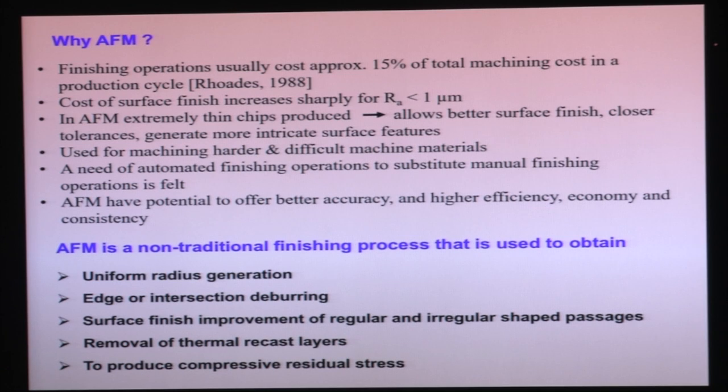and then we shall discuss the applications of this abrasive flow finishing process. So first, why does this abrasive flow finishing process come, why do these super finishing processes come? These super finishing processes are required nowadays because the surface finish requirement is in the range of nanometer. Sometimes we need angstrom level surface roughnesses. Suppose we need the lenses used in a missile, in those lenses we need surface roughness in the range of nanometer or even angstrom level.